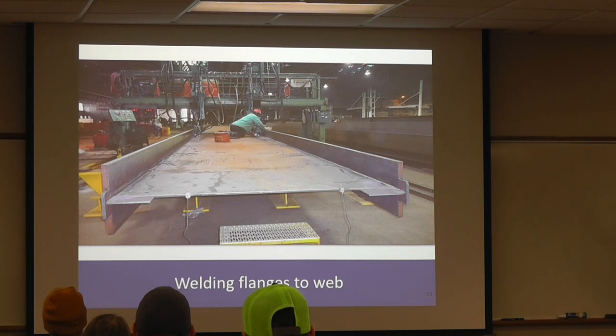Now remember, I said these can be up to 15 feet tall, which can be a really hard thing to support. So most of the girders are fabricated on their side like this, unless they have a really significant horizontal curvature to them. So they're going to lay that slab out.